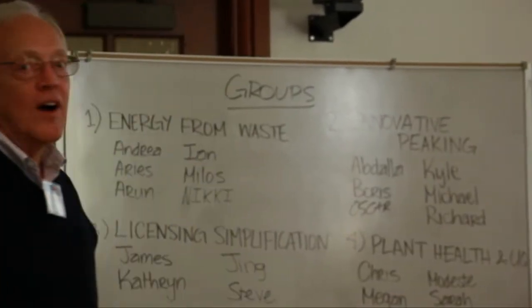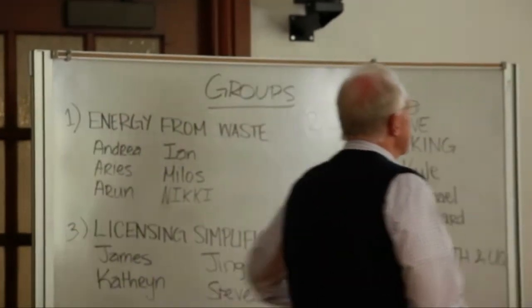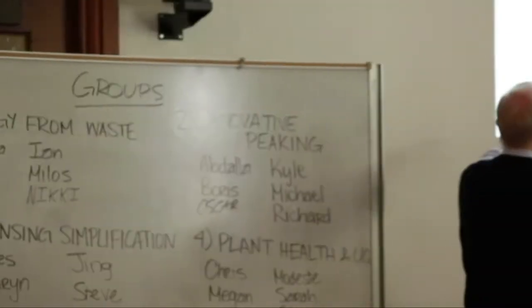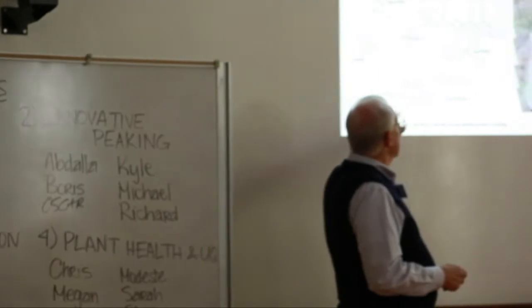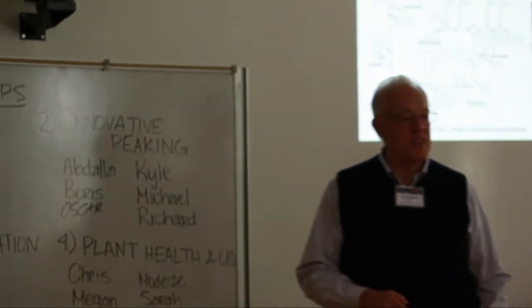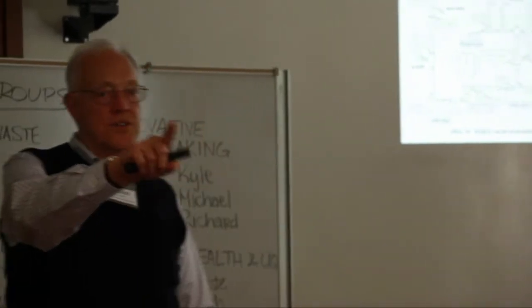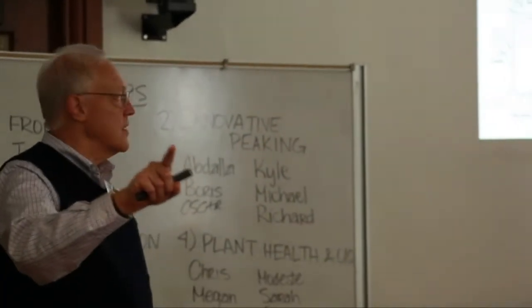Here are the BWRs and the areas of susceptibility, all these little places that are shown here. This is where we got intergranular stress corrosion cracking in the stainless steel boiling water reactors as a result of decisions like you're describing.